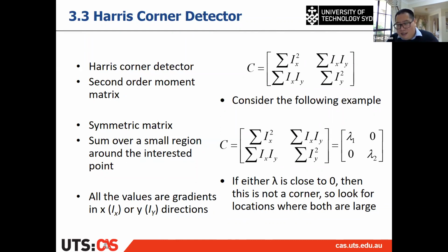Then the Harris corner detection is mainly about detecting corners. For example, why we were using Harris corner in that case is that all the photogrammetric images are of civil areas, which means there are a lot of buildings on the image. For buildings and roads, it's quite easy to extract the corners. There are a lot of corners there. So Harris corner is mainly detecting corners.